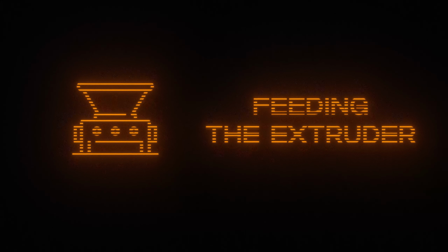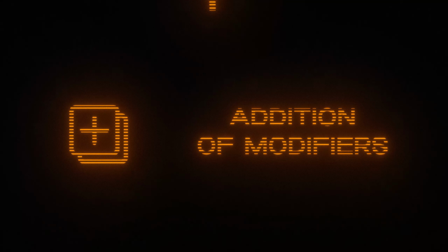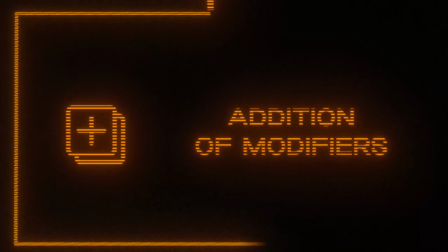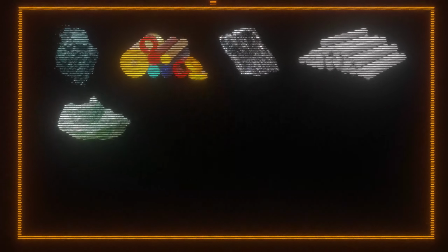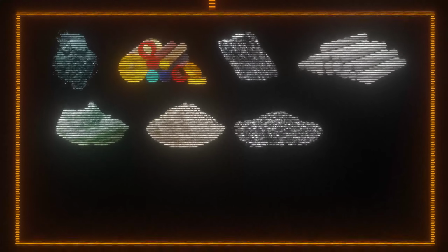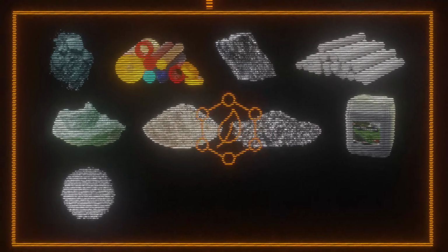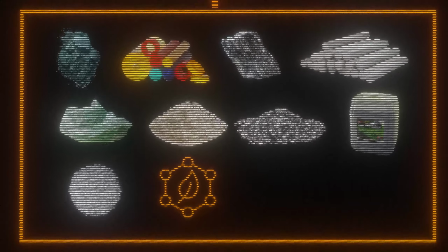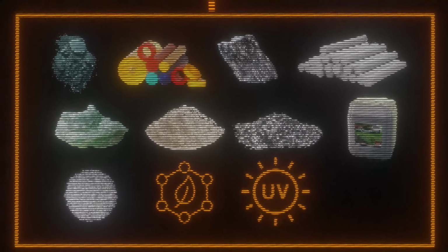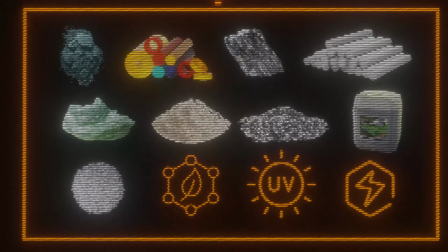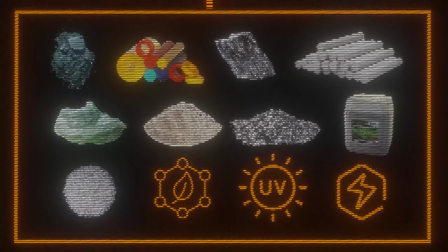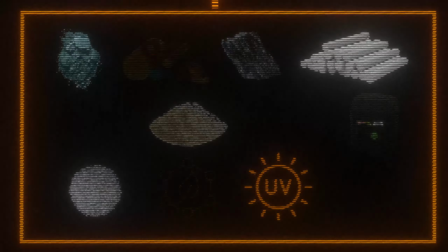2. Adding modifiers. The following are added to the molten polymer. During the compounding process, various additives are used to improve the properties of polypropylene: carbon black, elastomers, rubbers, graphite, chalk, calcium carbonate, talc, quartz flour, carbon fillers, plasticizers, stabilizers, antioxidants, which prevent oxidation and thermal decomposition, UV stabilizers, which protect against destruction under the influence of ultraviolet light, anti-static agents, processing additives, anti-blocking agents, flame retardants, and others. Dozens of different additives, in quantity up to 50% by weight.